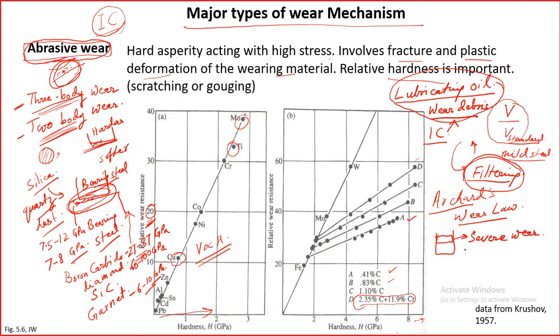Okay, as well as crankshaft and the cam, all kinds of wear will take place here. So filtering is very, very important, and just filtering also may not be sufficient. So at some interval of time we must go for oil change. Oil change is needed because the lubricating oil now contains so much wear debris that the filtering is not possible. It is very, very dirty.